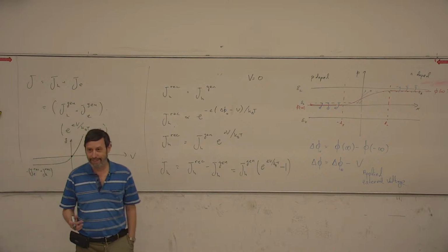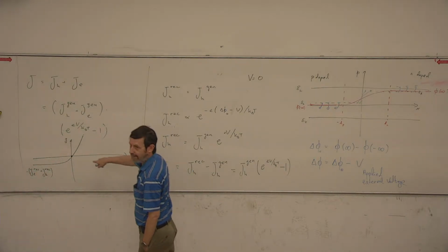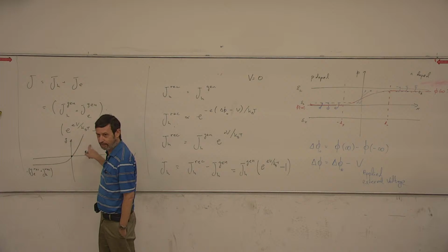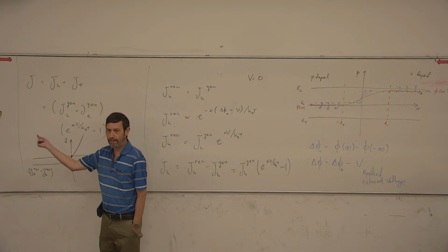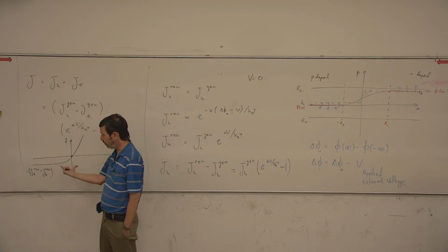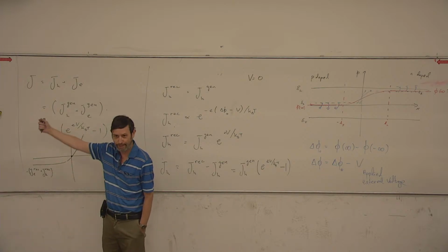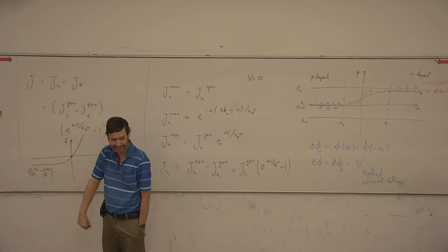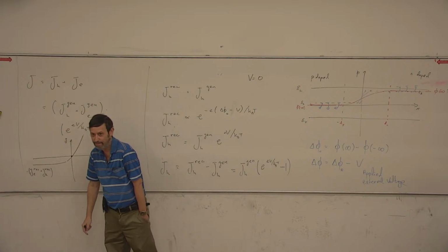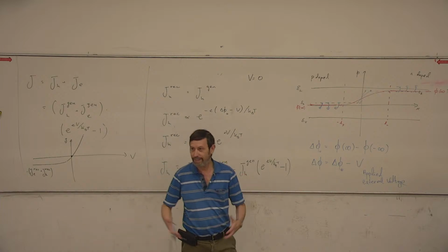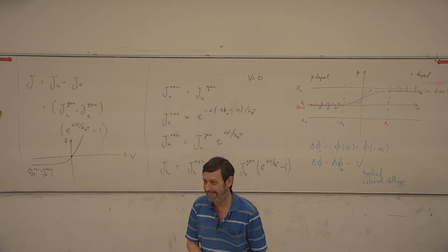Basically, you put in an AC component, so you'll get current going in one direction and then the other. You put in a diode that will go in one direction, but almost not in the other direction. So it's straightening up an AC current.